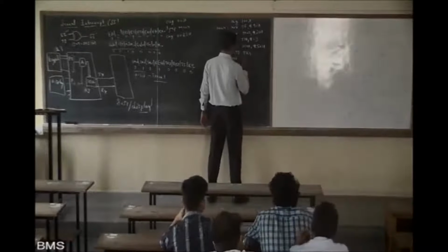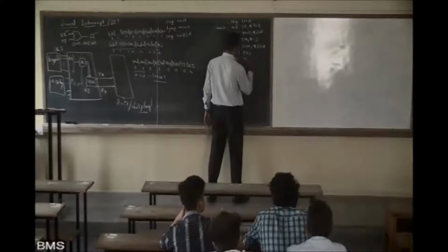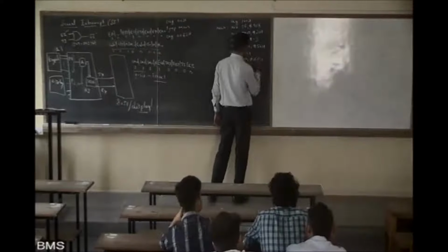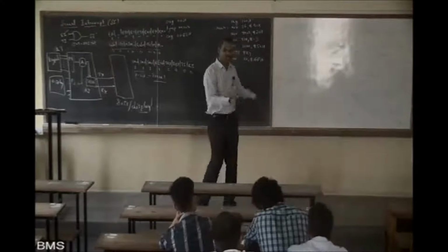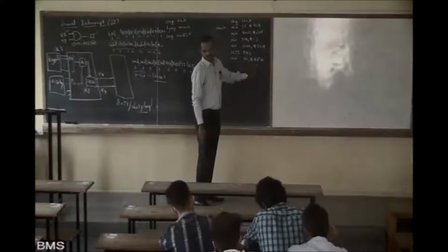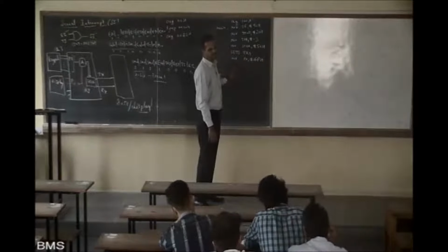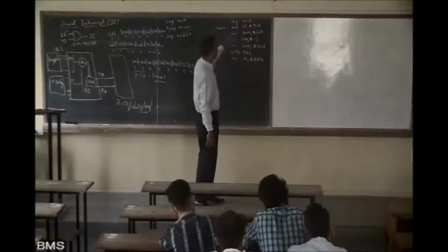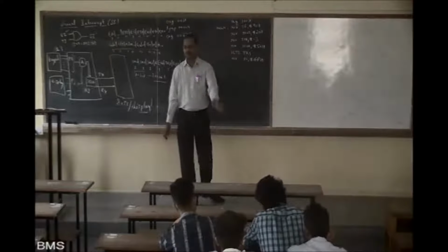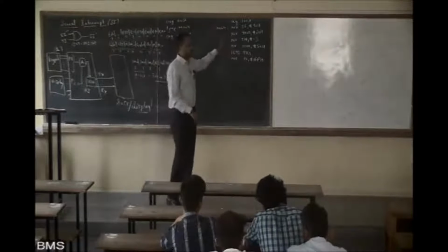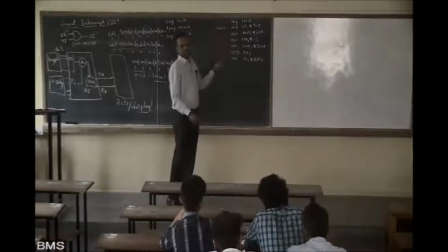Move P0 comma #0FFH. When you reset, by default it will be there. Still it is suggested to do this, only as a precautionary method. Now all setting is done. And this setting has to be done only once. Next, what should I do?